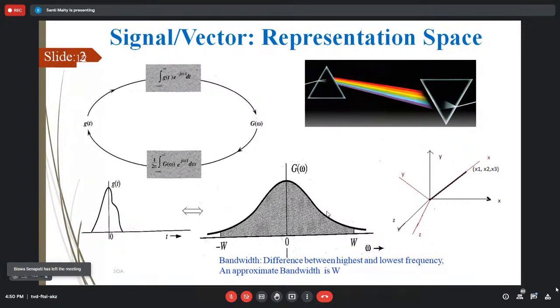But in reality, the signal has two things you need to consider. Communication people may bother about the bandwidth rate, and of course, communication people also think of the information rate. The computer science people can think of the information rate too. Is the information rate lower than the bandwidth rate? I mean, is every frequency component equally important from an information point of view? If not, can we go for sampling at the information rate rather than the bandwidth rate?